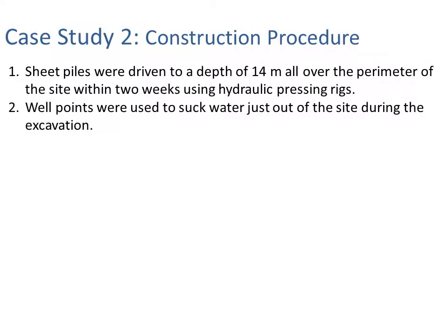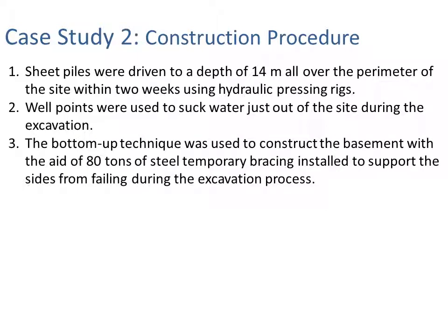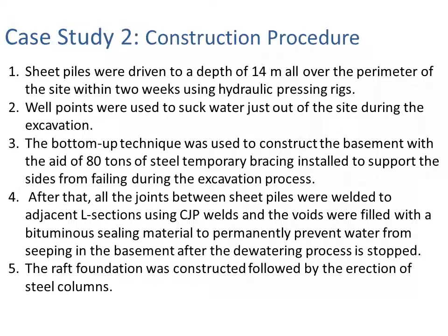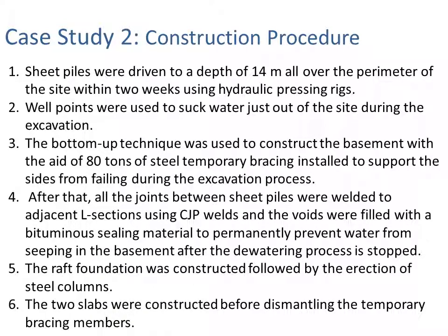Well points were used to suck water. The bottom-up technique was used in such a case because it's a small-scale project and you do not need a massive amount of temporary bracing here. The raft foundation was constructed. Then the two slabs were constructed before dismantling the temporary bracing.